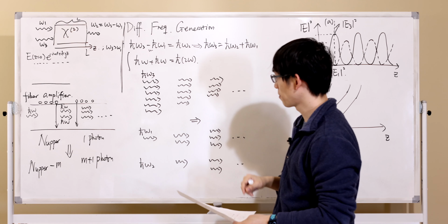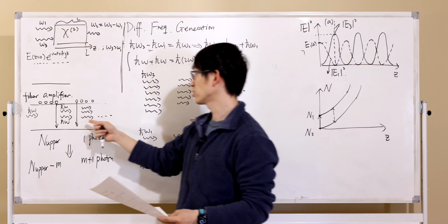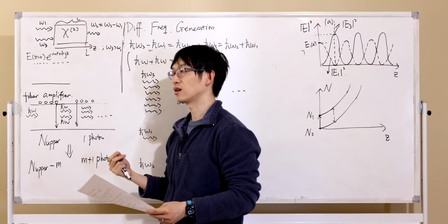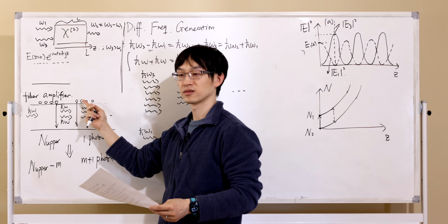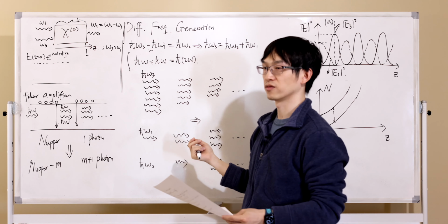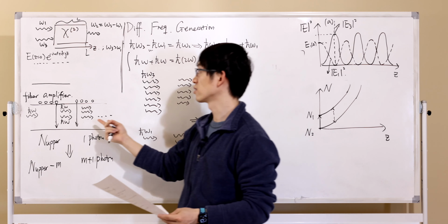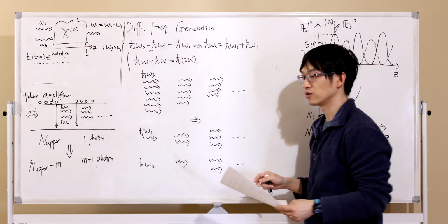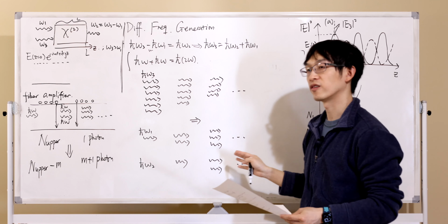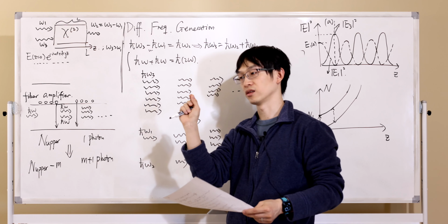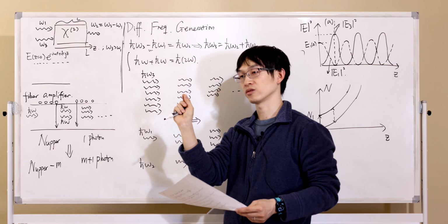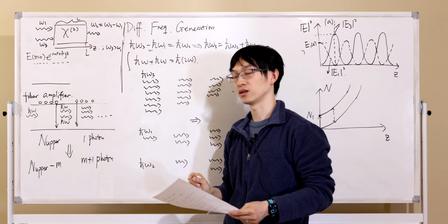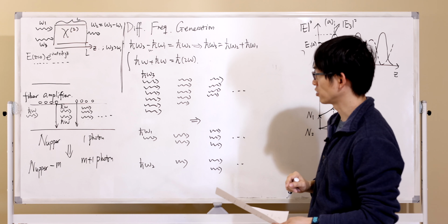The first is that if your electron needs to go down and go up, go down and go up, that actually takes time. So a parametric amplifier is very, very fast compared with a conventional amplifier. A parametric amplifier is often used to amplify femtosecond lasers, laser pulses with a pulse width of a few femtoseconds. So that's one use of a parametric amplifier.